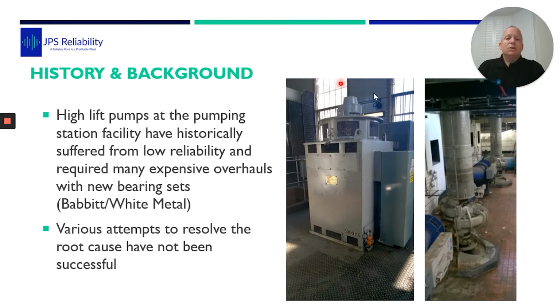These are large motors, 5,000 kilograms, about 3 meters high and about 1 meter and a bit square. Sleeve bearings. At the top is a tilting pad thrust bearing and a radial tilting pad bearing, and it's a tilting pad radial bearing at the bottom, and it's got a 6 meter cardan shaft down to a pump.